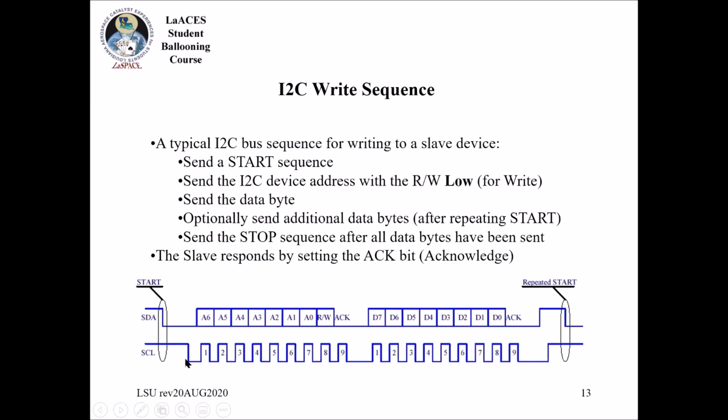And then this is all in reference to the clock. Depending on the device, sometimes you'll see that it's on the leading or rising edge, or the falling edge. Whenever you see something like that, that is when the data is going to be sampled. So the clock starts here. Whatever the status is, high or low, at the time of the rising edge of the clock, that is when that information is going to be read. Or if it's on the falling edge, then it'll be read on this back side of the pulse. So the clock is important. It needs to sync up to the data, and you'll always be looking at that rising or falling edge where your data is being lined up.